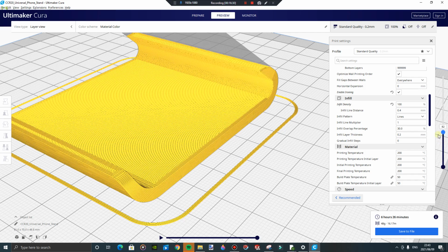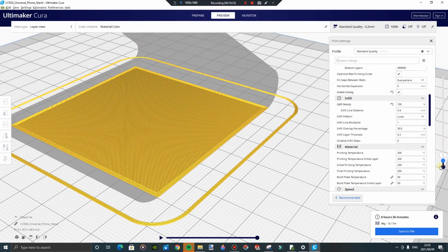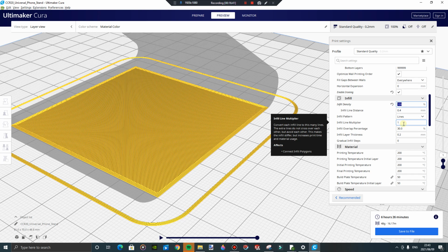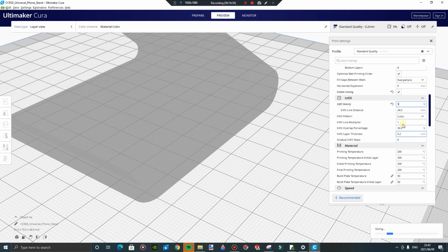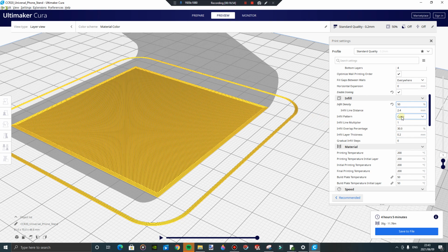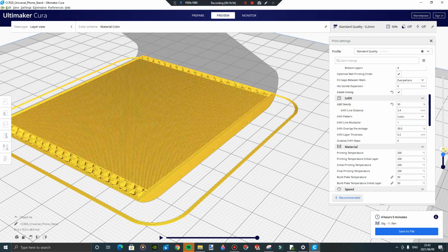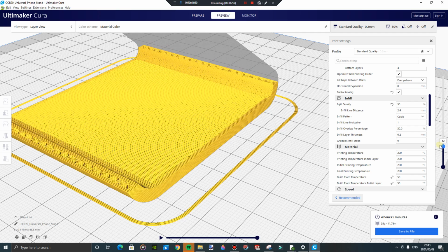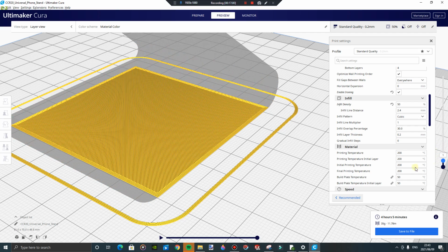I've seen these structures fracturing and breaking when printed at 100%, because remember, at the end of the day, FDM 3D printing was not intended for creating solid objects. So depending on your application, you want something like 50, I'd say 80% maximum. You wouldn't go more than that.